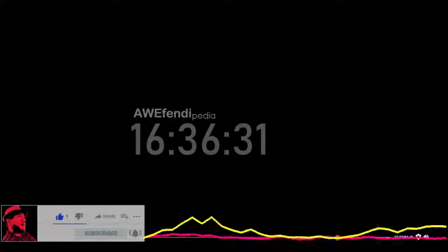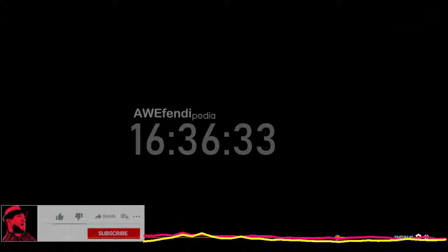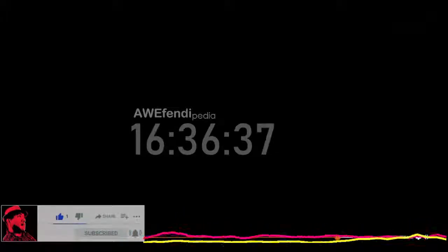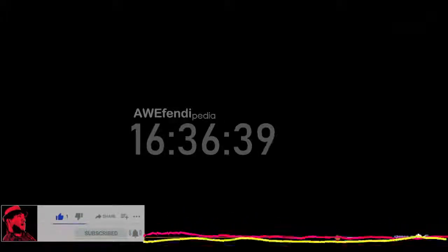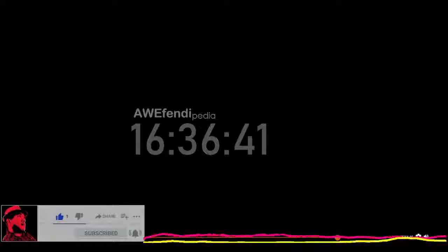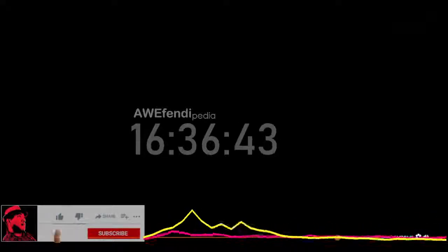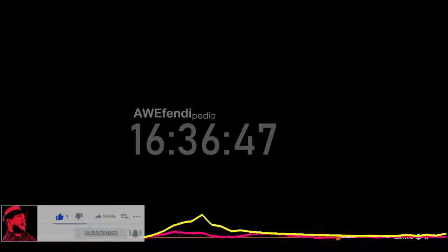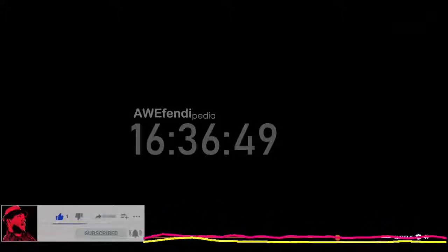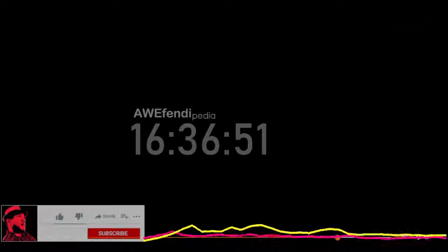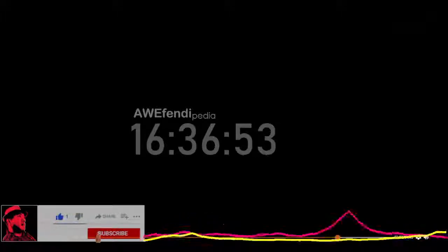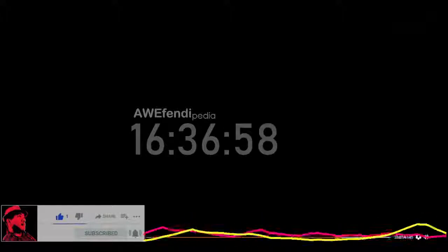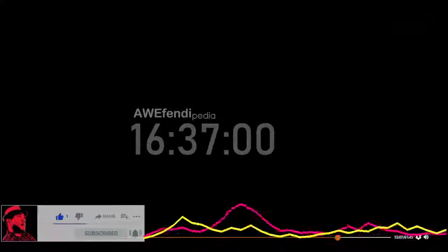On my pipes here, we can see that it's given me the length of the pipe. It's putting a flow arrow there. It's annotating the inverts in and out. So once I have that annotated, how to set up annotations is a whole other class that we may do later when we get to drawing production. But again, the power is in how we've set up feature definitions and our text favorites and all that kind of stuff. Once I have that annotated, I just see that we're running out of time a little bit.